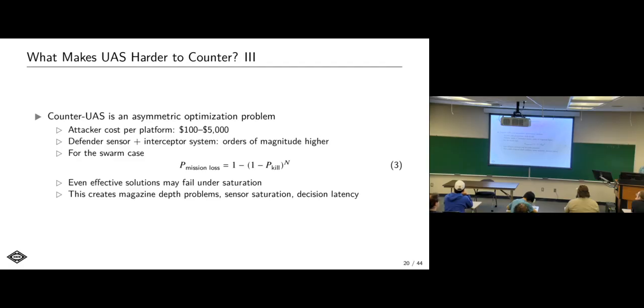You can make it use radar, you can make it use a camera. If you get fancy, you can try to do thermal tracking. Drones make noise, so you can use microphones for acoustic location, that kind of stuff. You can get some thermal cameras pretty cheap from Adafruit too. They're not great, but you can get some basic ones that hook up to Arduino and give you enough to get a couple of pixels on target, which gives you your basics of IR tracking.